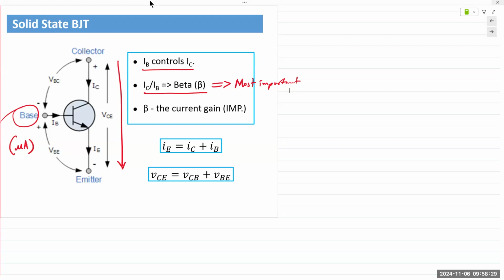And so it's an acceptable range. Even in your JFETs, when you all did the pre-labs, you would have seen a range for pinch-off, VP. There was a range given. The reason for the range is because you cannot manufacture it exactly the same. Okay, so when we look up the spec sheets, all of these parameters that are specified by the manufacturer will always have a certain range, and that is because of the variations in the manufacturing process.